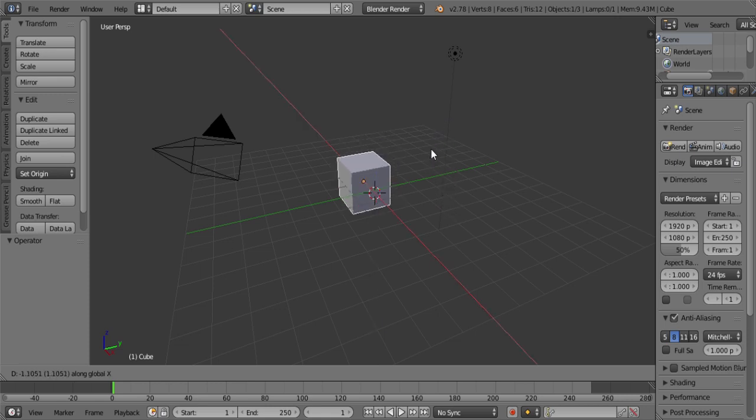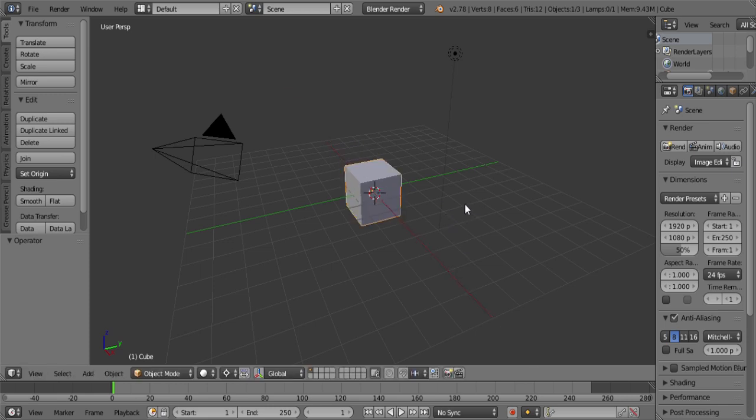I press X and you just have to press it once, you don't need to keep it pressed. And then I hold down Control and Shift and it's making really refined steps along X. Same goes for rotations. If I press R and I hold down Control, it's rotating in steps of 5 degrees. Including Shift as well, it's moving at 1 degree.